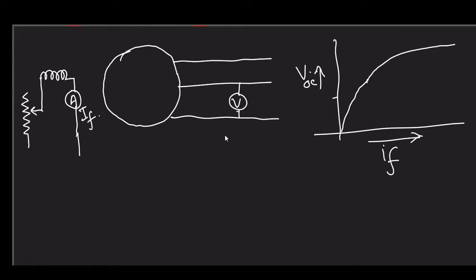Anyway, let us move to the next one, that is our short circuit characteristics. What we do in case of short circuit characteristics is short any two terminals with a solid conductor and short the other remaining two with an ammeter. Here we are assuming that this ammeter has zero resistance, and what we get